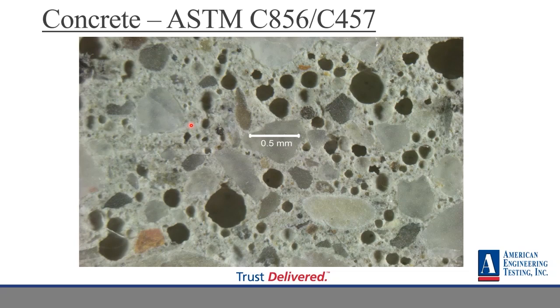It might counter-react with the other particles, if that makes sense. But from the stuff I've read and the stuff I've seen, I haven't seen bulk distress from that. And from what I've read, that glassy texture in those expanded aggregates does not cause alkali-silica reactivity.